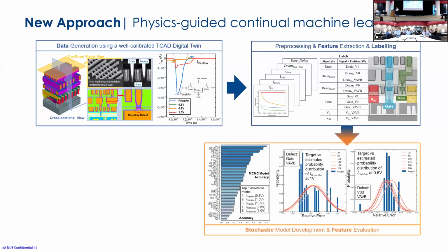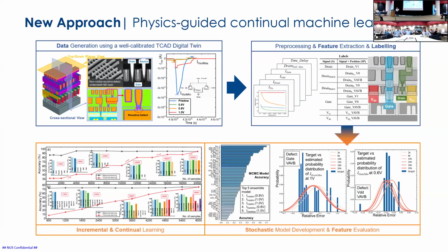We're currently working on an approach based on a physics-guided Bayesian method, where we understand that the defect distribution and defect responses have a certain signature according to a certain distribution, but we don't know what that distribution is. So we loop it through the models to inform and continuously teach the machine learning model. We have done fairly sophisticated approaches based on local interconnect, which is a big problem in all the advanced technology today because of the density as well as the topography issue.